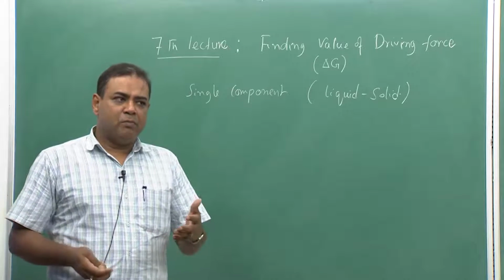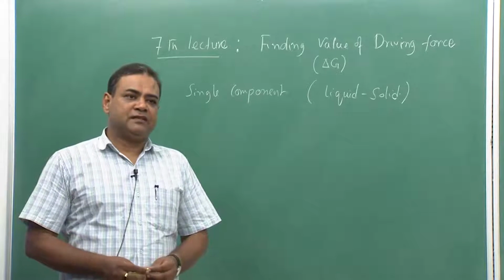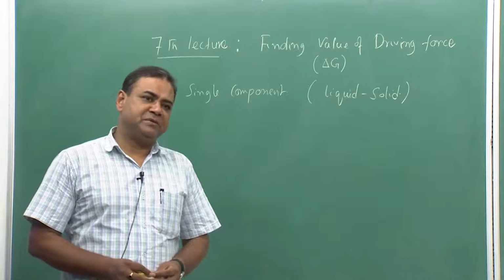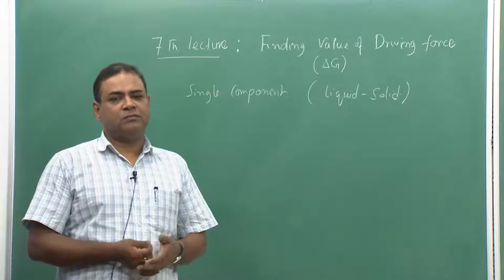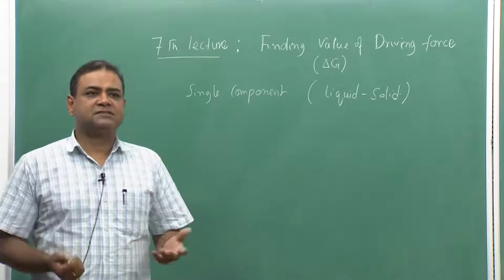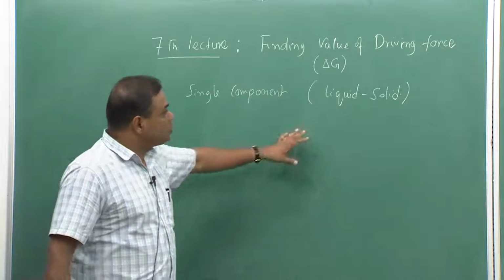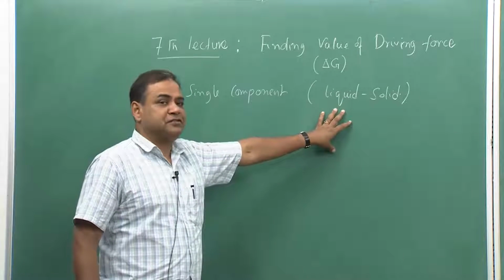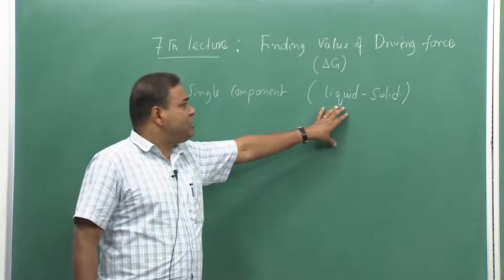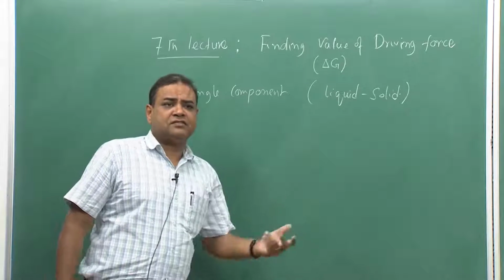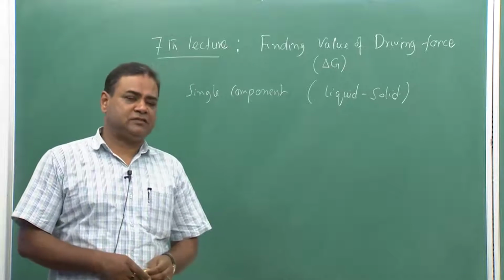Mostly in polymers we get glassy polymers, and at the same time we get a mixture of crystal and glass, which enhances the properties. In those cases this will be a very vital transformation mechanism. Many glasses we also get in metals, and we call them metallic glass.